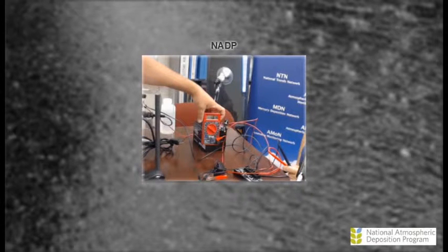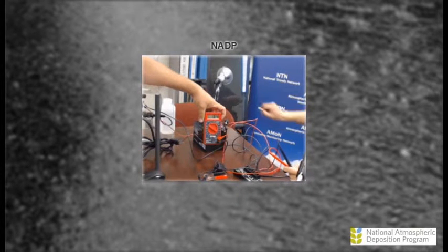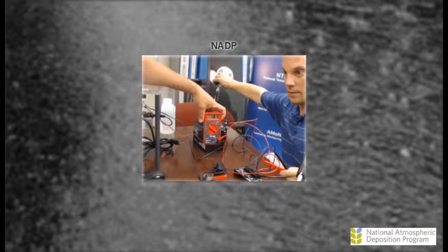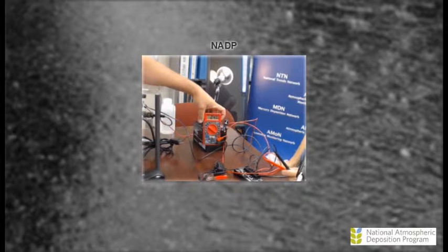Just under the ambient light in our office here, we are producing about 1.8 volts straight out of the solar panel. When the sun comes out, we turn the light on the solar panel behind us, we can see the voltage climbs up. We're about 2.5 volts. If we were in full sun, unregulated, we'd be about 20 volts here. So it's above the capacity of our battery to take it.